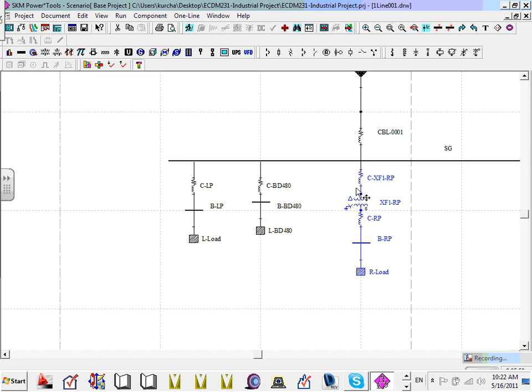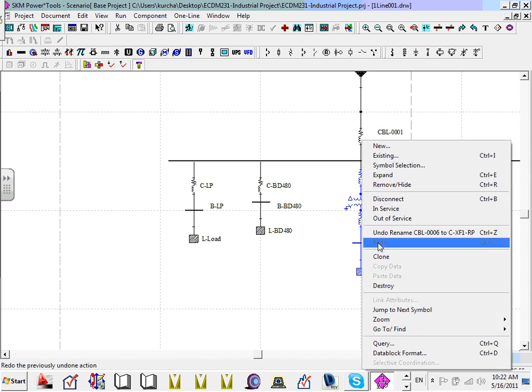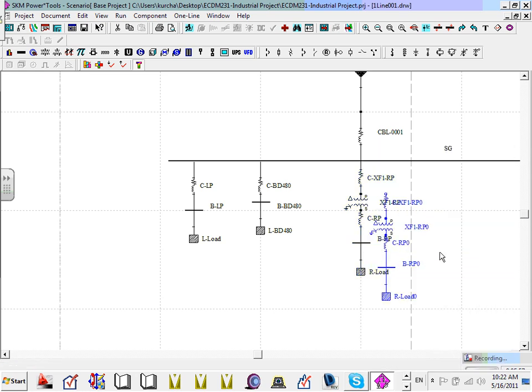So right click on it, and regardless of what you believe, you're going to believe in cloning at least. Make sure you don't click anywhere, guys. After you clone it, don't click anywhere, because that's where it gets mixed up, until you get this move signal. Can you guys see that move signal right here? Now, hold the shift and drag all of it together. It allows you to drag it all together. Now it's connected, drag it down, adjust it.